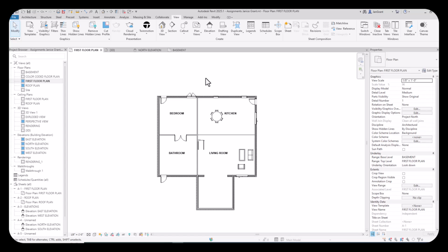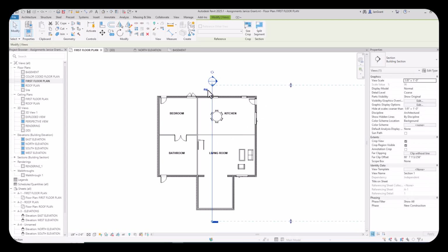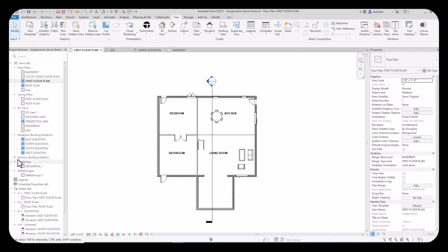All right. So when you draw a section, you can decide on which side to put the head and which for the tail, for which way the numbers go. So on the View tab, go to Section. See, now if I click here and I bring my mouse down, you see how it's facing to the left? But I'm just going to go ahead and click, because I'm going to be able to click on these arrows right here to switch the view to look towards my stair. And now I have another section to work with.